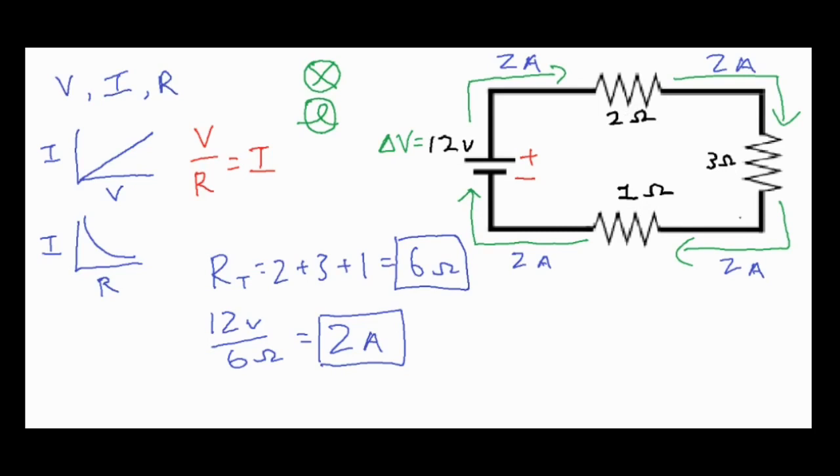And what we can do is we can do 3 minor calculations by taking the R and multiplying it to the other side, and then saying V is equal to I times R. Now, if we did that, we can find the individual voltage drops for each one of the resistors. So let's go ahead and do that.